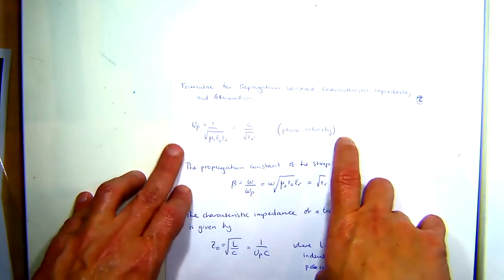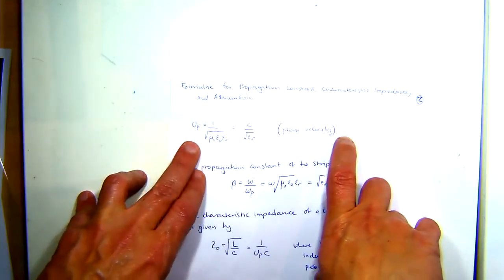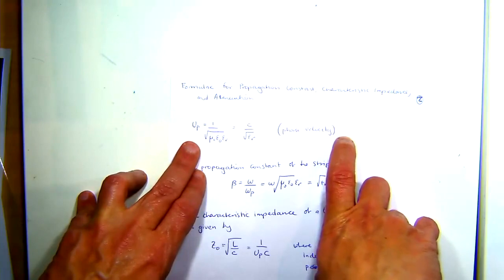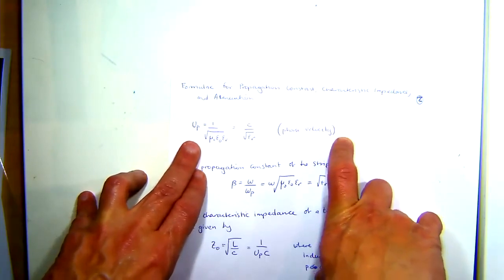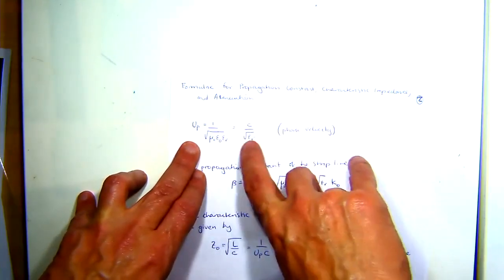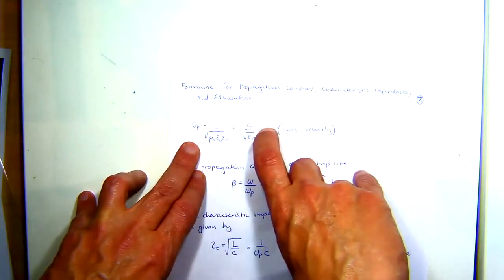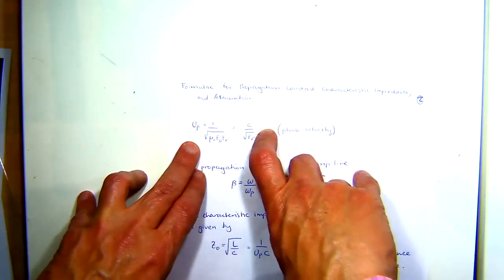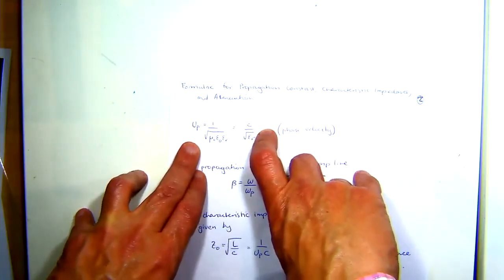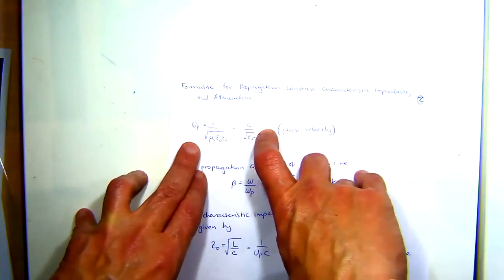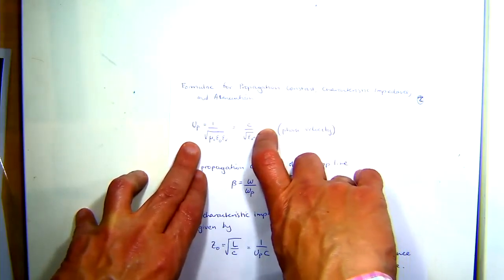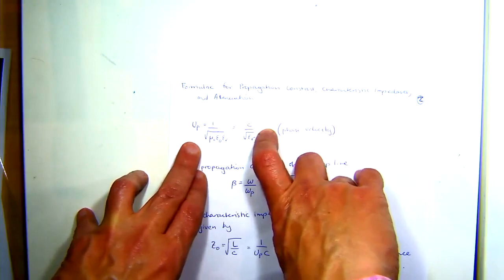So therefore, if you want to work out what the speed of light is in your particular medium, you always use this formula, provided it's not a magnetic material. And remember, these PCB boards are usually dielectric, and usually they're some kind of woven glass, like FR4, which is a woven fiberglass.